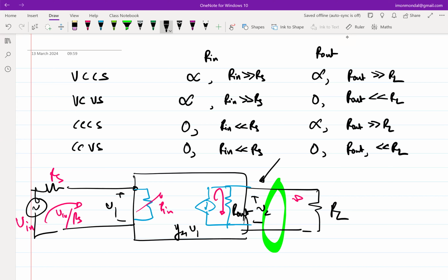The transistor is essentially a current source, because the current IDS is not dependent on VDS. Since you can keep on changing VDS as long as the transistor is in saturation, the IDS isn't changing, which means it's a current source. So by default, a MOSFET is a VCCS. Next, we are trying to see if we can design a VCVS using a transistor.